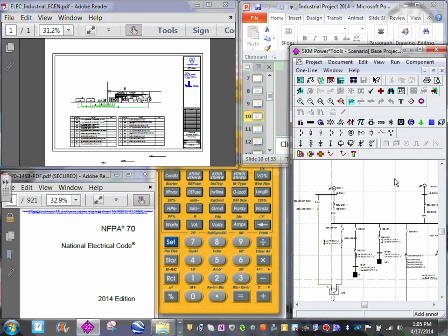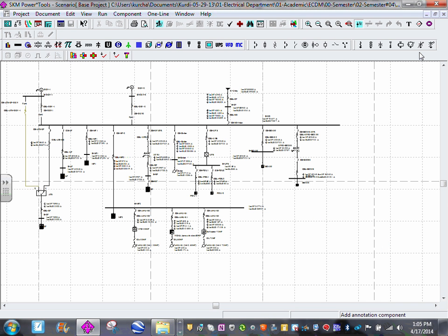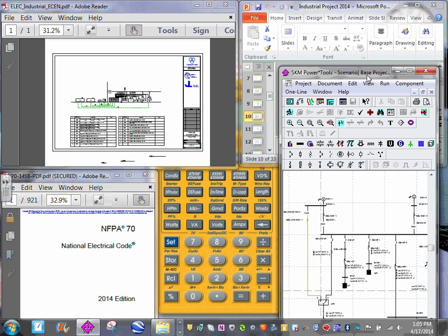So I have multiple things, and I have access to SKM. That's why I asked about engineers. If you have access to SKM, it's great, guys. It's a resource in checking your sizes and all this stuff, especially overcurrent protection device sizing for transformers and chillers and rooftop units and air handling units. So it's a great tool if you have it. You don't have to have it.